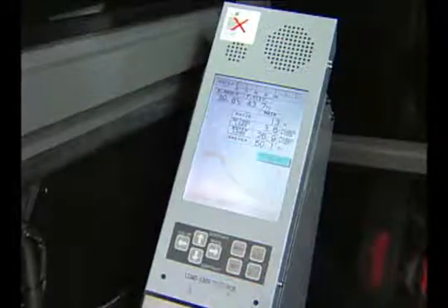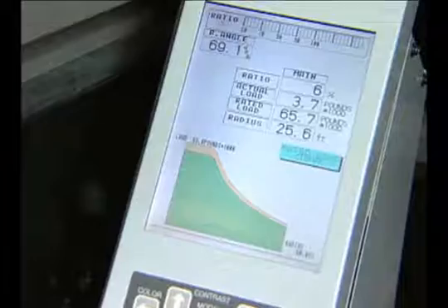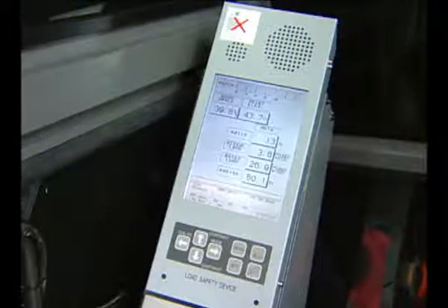The three main parts of the Kobelco LMI include the main display, which works with the main machine's total controller, the hardwired load cell located at the dead end of the boom hoist cable, and the angle sensor located inside of the boom base section. We will now discuss the main monitor display inside the operator's cab.